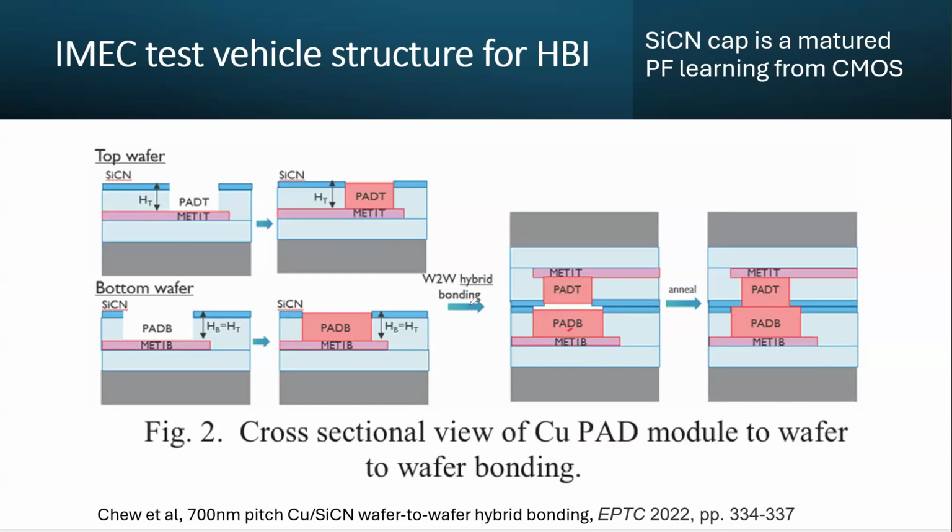This is the wafer to wafer bonding. So when you flip it, it's copper, flip it, and anneal. The atoms start to anneal and form it. And there are many intricacies. How do you deal with this kind of recess? How do you form this gap? They are all very critical. And then how do you do the anneal? How do you clean the surface so it will have a perfect bonding?